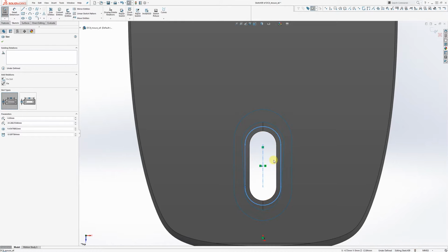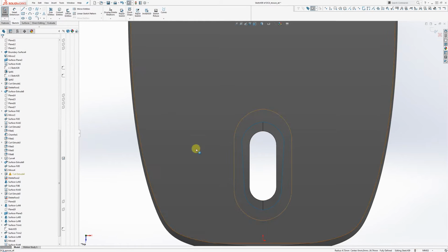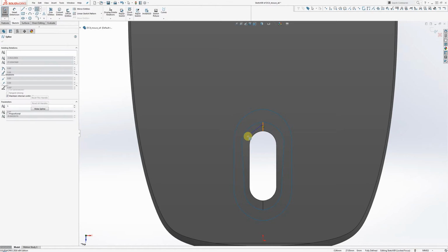This is not going to work at all, because if you just look at the taper on this upper surface, it's not a proper slot any longer. So I'm going to delete the slot and just draw my own curve. It's usually the hard way if you're wondering how to do stuff. If you're wondering, is there an easy way to do this? Nah. Usually the hard way is the easiest way to get something done.